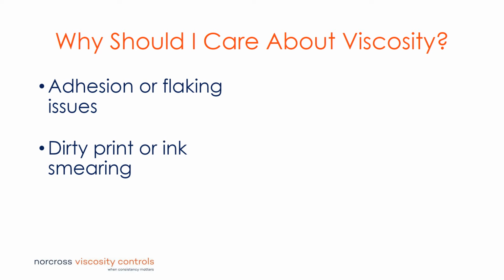Dirty print or ink smearing. If the ink viscosity is not adequately maintained throughout a press run, the ink viscosity rises and falls due to solvent evaporation and replacement. The ink may adhere to or build up on the plate, impression roller, or substrate outside of the impression area.